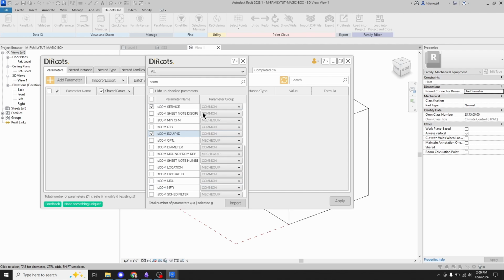This isn't going to mean a whole lot to you if you don't have the RevX shared parameters, so I'm not going to bother you with it. But you get the sense, right? There's a naming convention for all of our shared parameters. Model manufacturer. Some of these are specific to certain kinds of equipment, but almost every bit of equipment is going to have model manufacturer. Equipment ID, that's what our tags do. This is a square thing, so I don't need the diameter, but the length and width, if you want to report that on a schedule, that's nice.